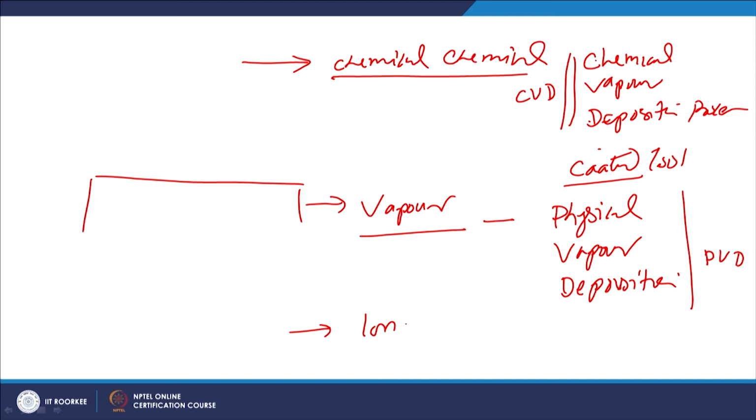So basically it uses the ions of the suitable medium, and they are directed at a high speed towards the surface of the substrate for modifying the surface metallurgy as well as the surface chemistry, in case of the processes like ion implantation. So these are the three kinds of the mediums which are used for modifying the surface chemistry, and accordingly the different processes are used.